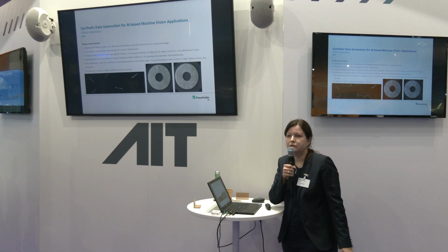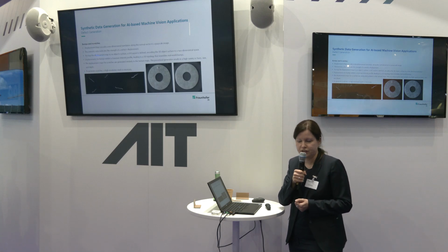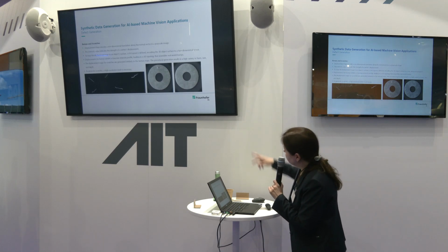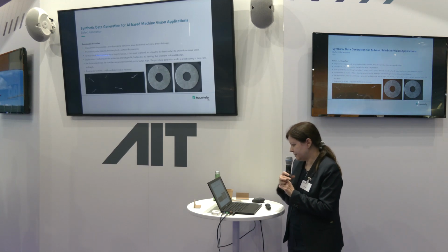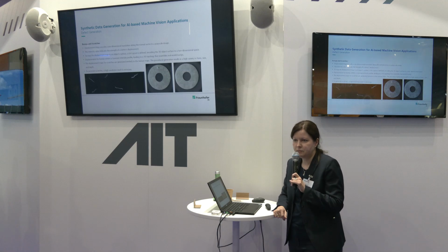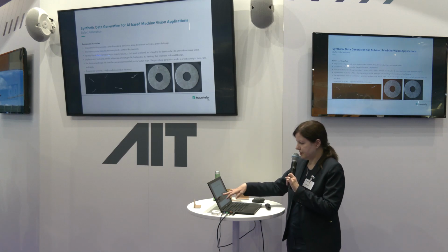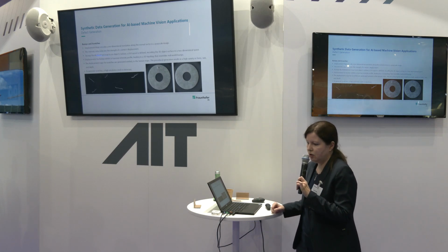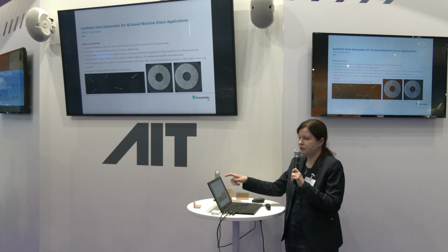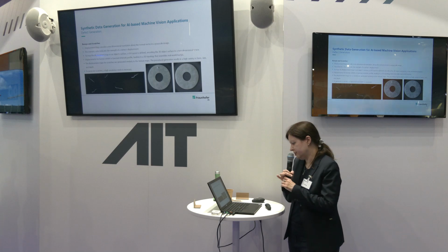And of course the defects, this is the reason why we want to simulate, we want to have enough defect images. For example, we have scratches here on these washers. These are metal parts, and we can simulate scratches by using these displacement maps. We put automated scratches in this UV map and put it on our object. So we have different kinds of random scratches with different length, different appearance on different positions on our washer.